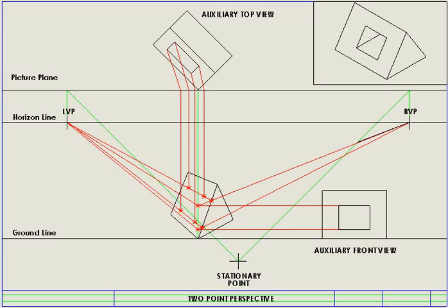Alright, so we are going to be projecting from our stationary point to find those right and left vanishing points, and also using the point that is dropped from the point that is touching the picture plane as an information bar. The information that I need from here right now is I need to be able to find this rectangular hole on this slant surface. We've also been given the actual triangular prism, or if you want to call it the gable roof, and we are going to now have a final look at how we're going to be finding those points.